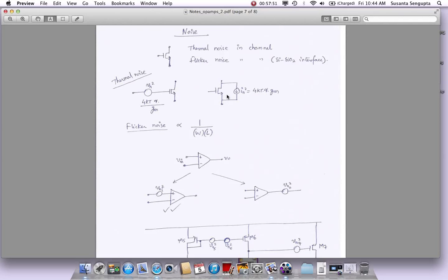Now there is another way people like to do it, and this is where you take the noise current, and if you know the effective transconductance Gm, you can divide it by Gm square. Remember, this is not noise current, it's In square. It is more like a power. So if you do I square R, noise power, and if R was 1 ohm, then I square gives you the power across 1 ohm. So here this is showing you the noise power in a superficial 1 ohm resistance. So we always try to use it more like a power in the power levels to do this.